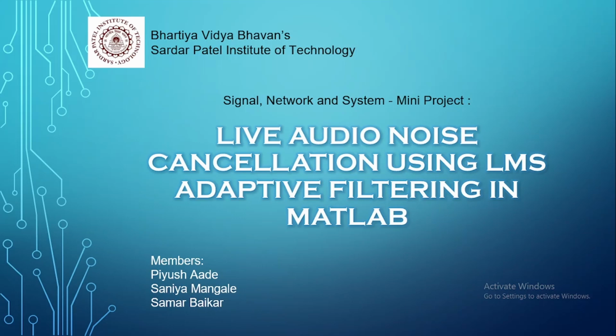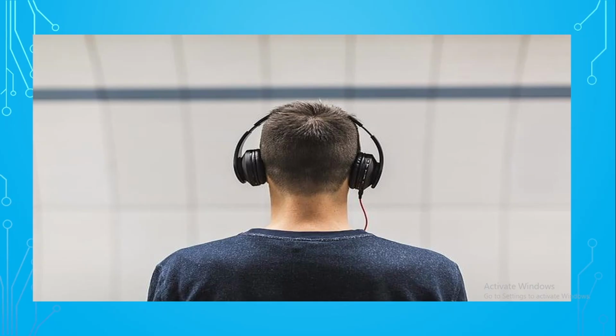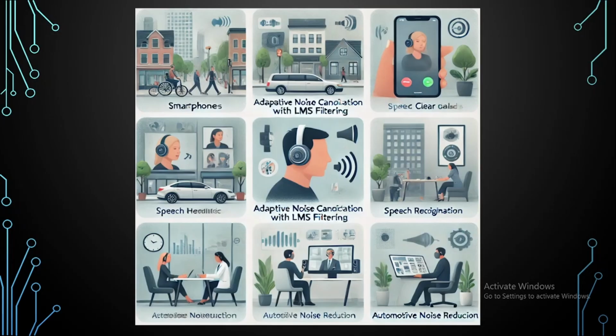LMS adapts to different noise environments in real time, helps to reduce unwanted sounds and enhance voice clarity. In this demo, we will record a sample, filter out the noise, and compare before and after audio to evaluate the noise reduction achieved. This method of noise cancellation can be highly effective in various applications, from enhancing call quality to improving audio clarity in recordings. By using adaptive filtering, we are allowing our filter to learn and adapt to the noise, making it more flexible than simple static filters. So let's dive in and see how we can implement this in MATLAB to create a powerful and flexible noise cancellation system.